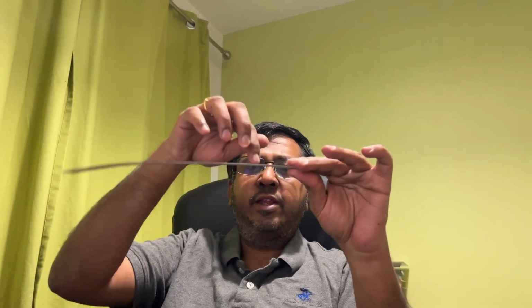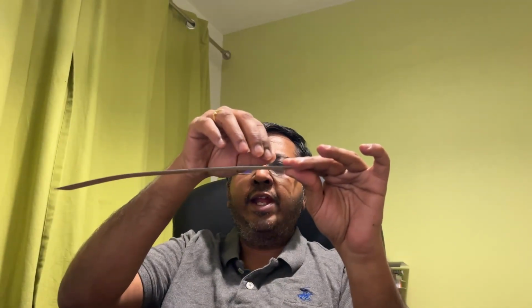So we have this total beam and we want to, let's say, approximate this. Here the mass is distributed in every point. If I take a point here, it has some mass. This point has some mass. Some point has some mass. It is continuous. So one can say you have an infinite number of mass points. We want to take this infinite system and say that mass is only here and here and here. There's no mass here. Mass is only here, here and here in a discrete system.